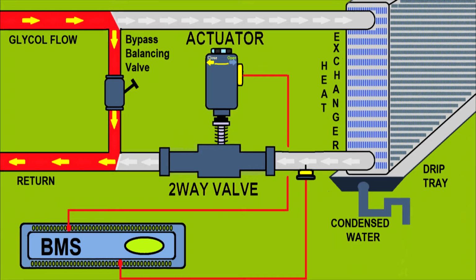Maybe it's not a usual thing, but sometimes we use heat exchangers that have the capability to heat and to cool the premises. So this heat exchanger will receive either hot or cold intermediary cooling or heating agent, and this is a situation in which I'm going to use a drip tray and condensed water, even if you see that this system in this moment is ready to run on heating mode.